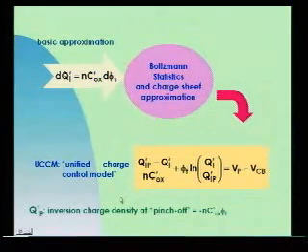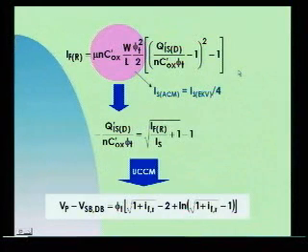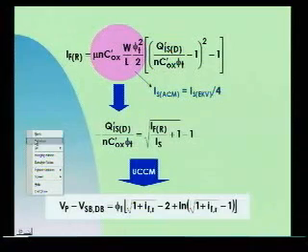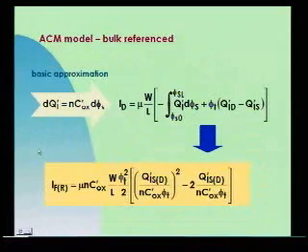So we can have the voltage to current relationship just by substituting. You can see that the expression that I've shown first here, this one, I can invert this and express the inversion charge density as a function of the saturation component of the current.